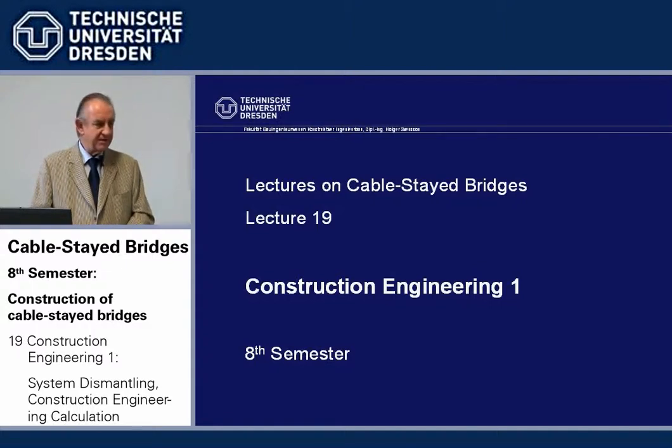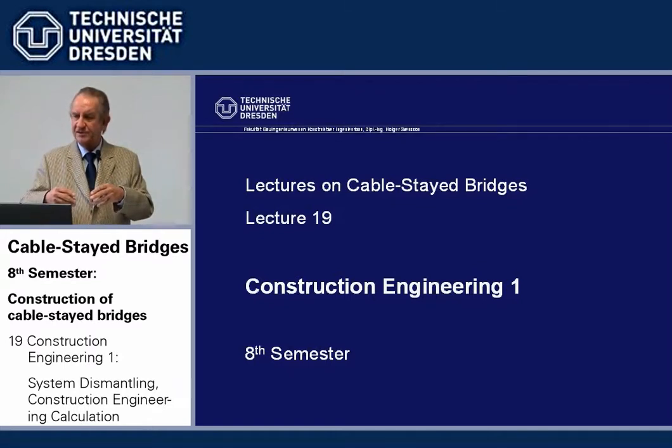We start by designing a cable-stayed bridge in its final stage. But to build the bridge, we also need to know how it's put together, under especially two points of view. On one hand, we must ascertain the safety during construction at each stage. The beam must not break off because we suddenly have too big loads. And in addition, we want to end up with the desired final stage, so we have to check whether the forces and deformations in every construction stage are those which we have calculated in the construction engineering, and if necessary, we can correct.